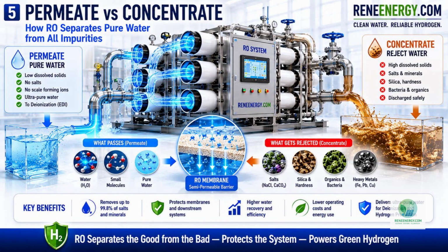This is one of the clearest ways to understand reverse osmosis. On one side, the system produces permeate, the clean water stream with low dissolved solids. This is the useful stream that moves forward toward deionization, storage, and electrolysis. On the other side, the system produces concentrate, the reject stream carrying salts, minerals, silica, organics, bacteria, and other impurities.